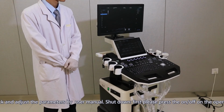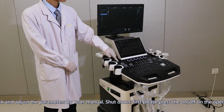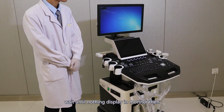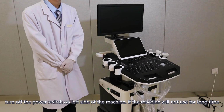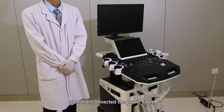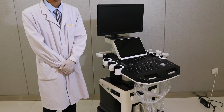Shutdown. Please press the on/off key on the operation panel. Wait until nothing displays on the monitor. Then turn off the power switch on the left side of the machine. If the machine will not be used for a long time, please disconnect the power cable and pay attention to protecting against dust and moisture.